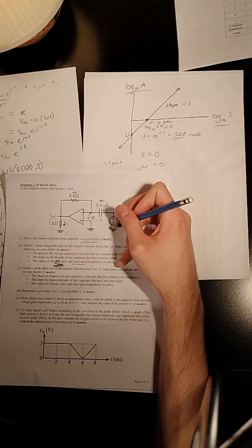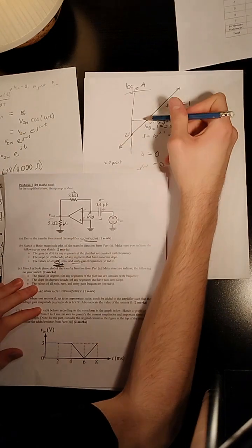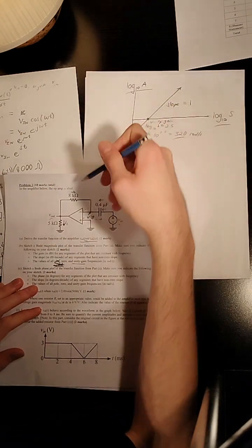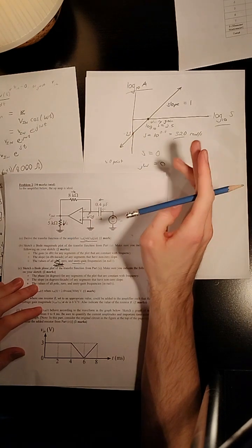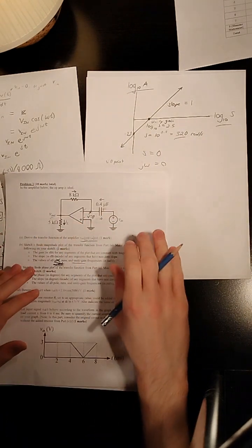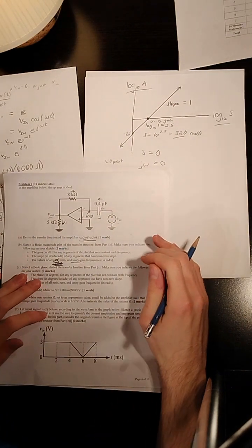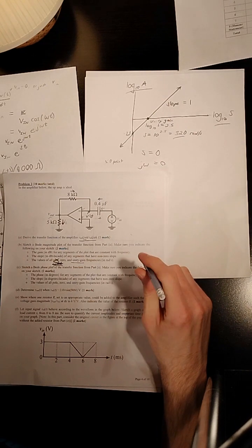Normally, with a negative 3 dB frequency, you need to know what the maximum transfer is. But there is no maximum transfer, right? If you increase V in, you're going to get pretty much as much current as you want through this capacitor, which means V out could have astronomically large gain. So don't worry about a negative 3 dB frequency in this particular case.